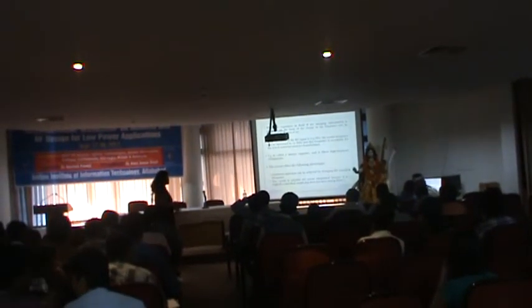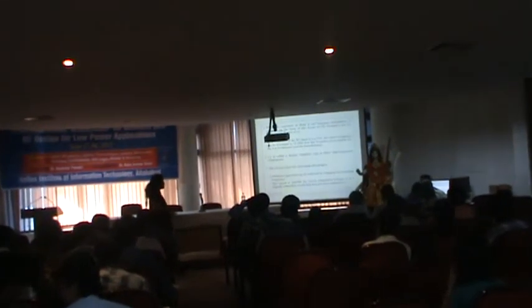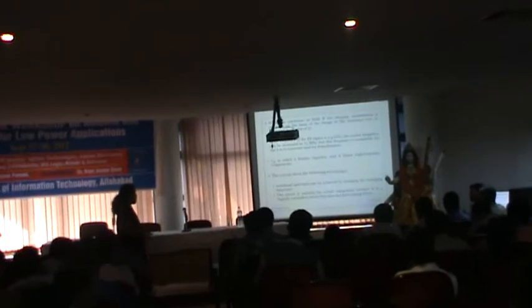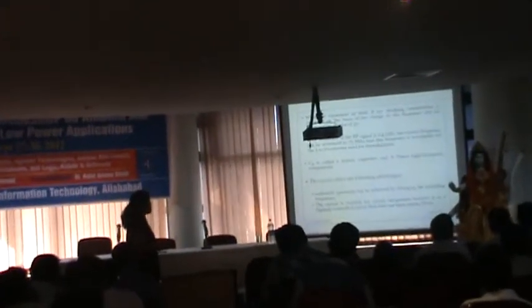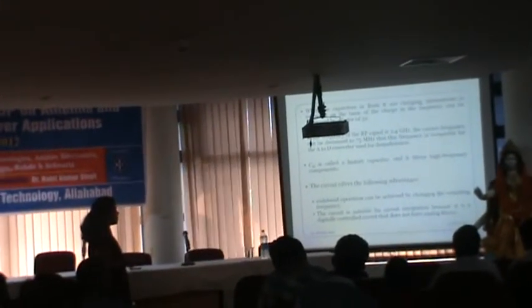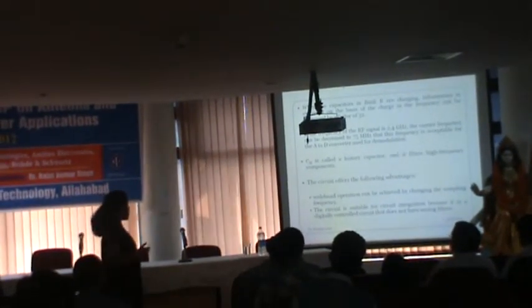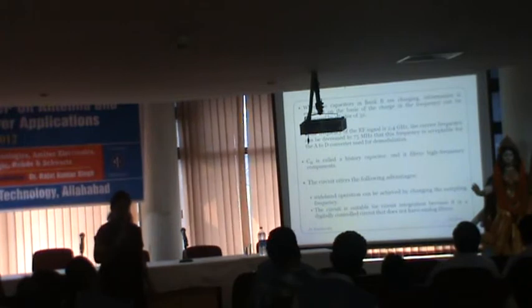Now, this kind of circuit offers the following advantages. For example, you have wideband operation, which can be achieved by changing the sampling frequency that we are providing. And the circuit is suitable for integration because it is a digitally controllable circuit, and it does not have analog filters in it.